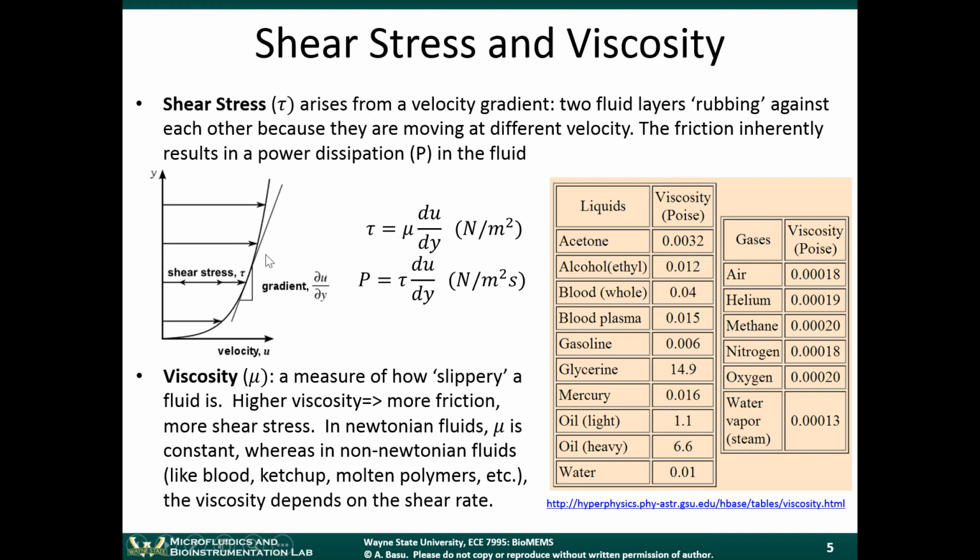Okay, a shear rate, by the way, is the same thing as this velocity gradient. It has the units 1/second. Another thing here, you can notice the gases here, they have a much smaller viscosity than water does, but it's not zero. As long as you have molecules and there's some friction between the molecules, there will be some viscosity. The only way you can avoid viscosity completely is if you have vacuum.